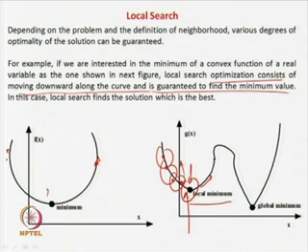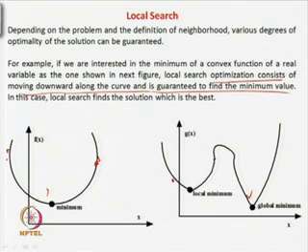But actually this is not, because this was the best solution only locally, but if you can somehow throw away this best solution for the time being, then you can jump over this and you can find the global minimum. This was a local minimum. So local searches will get stuck in this type of local minimum if your function is not a convex function. In the case of 2-level Boolean minimization, they are never as smooth a function as this. Therefore our heuristics always get stuck in local minimums, and generally we are not able to find the global minimum, which is the optimal solution, the most optimum solution.